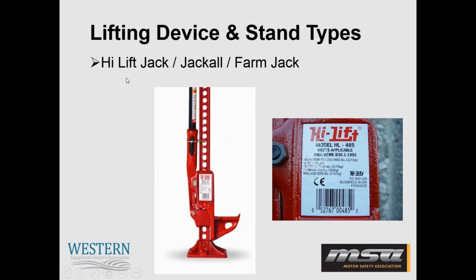Then we also have our high lift jack. Some people may refer to it as a jackall or a farm jack. And we see these pretty much everywhere we go. But what I really want to emphasize today is if you do have these types of jacks at your facility, check if it has a label on it that it meets a standard. So it needs to be tested and rated by a standards association. As seen on the picture on the right, this was rated by ANSI, the American National Standards Institute, as well as the ASME. And it talks about its rating and capacity right on the label.